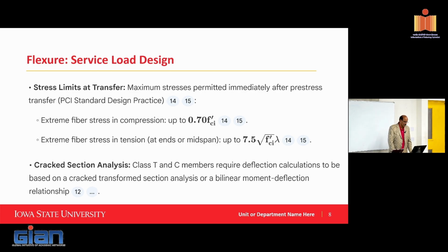And that's something you need to calculate and make sure of. If you're designing and asking a precaster to fabricate it, they will go through this calculation and make sure that the member is not going to crack. If the member is going to crack, for example, they can introduce some temporary measures to deal with that. For example, they may put in some additional strands. Again, strands are pretty cheap, in the whole sense, right? It's a fair statement. They waste a lot of strands, and throwing in one or two strands doesn't hurt. So sometimes they will put in additional prestress.